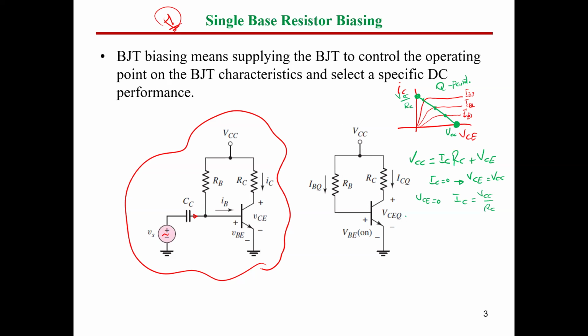So we can say, after getting the values of RC and VCC, the value of IB, the base current, will be IC divided by beta, and beta is our transistor's and should be defined as well. And from that, we can get RB from this circuit right here. So we can say the value of, or the waveform right here from this point to ground.